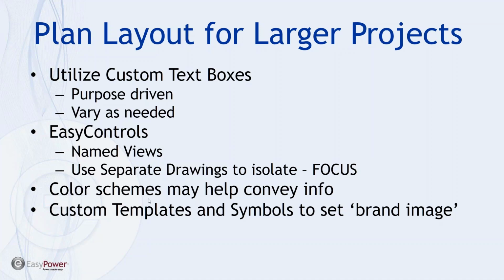Likewise, the ability to use color schemes in the OneLine can be very useful depending upon what we're trying to convey, and a lot of times this can be redundancy that needs to be color-coded, or it may be the importance of a particular load or a set of equipment that may require heightened attention from my maintenance staff for whatever reason. It could be a safety system, or it could be life support, or whatever.